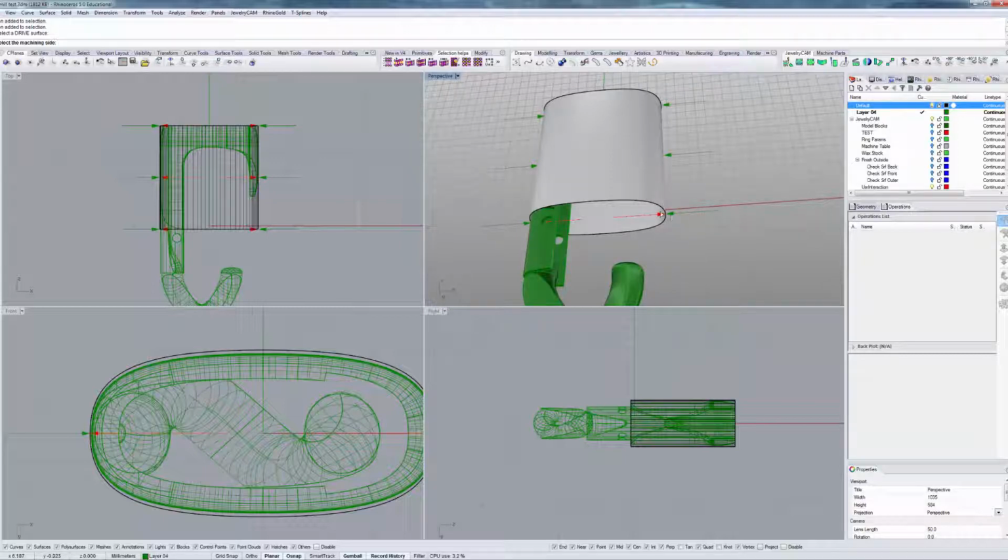The green and the red arrows generally suggest which area you're meant to be machining, green arrows being the outward surface. And if you find that you create your extrusion or sweep or whatever, and instead on the outside you have red arrows, you could always use the direction command to invert it. But Jewelry Cam will let you select either side, the inside or the outside.